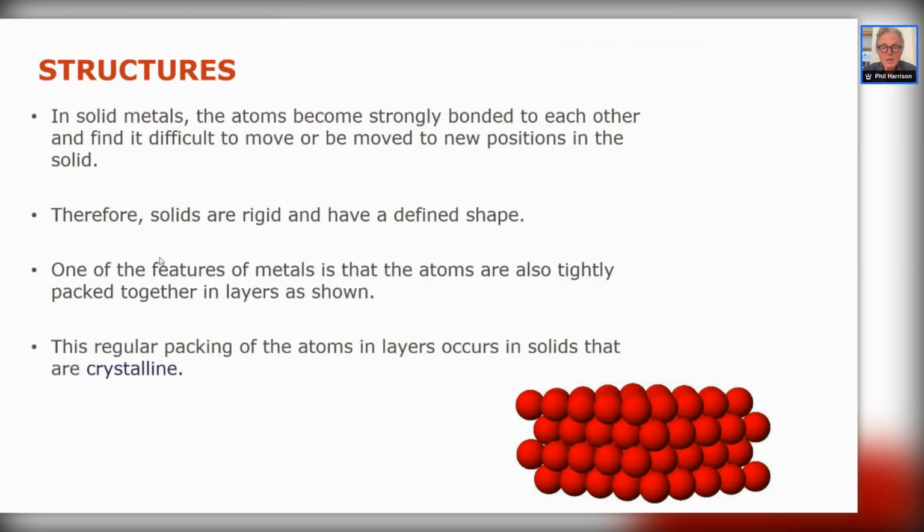And also how these crystals are packed together defines how they deform. Metals have things called slip systems in them. They have slip planes and slip directions where these planes of atoms will glide or slide over each other in specific directions. The more number of slip systems there are, the higher the potential for work in that material. For example, face-centered cubic and body-centered cubic have far more slip systems than hexagonal close-packed, so they do work easier.